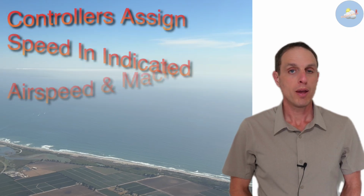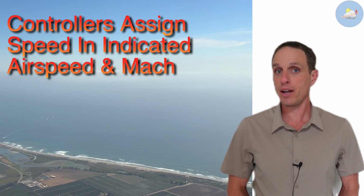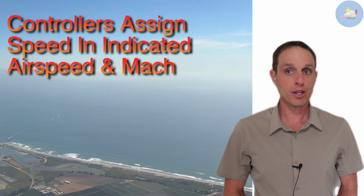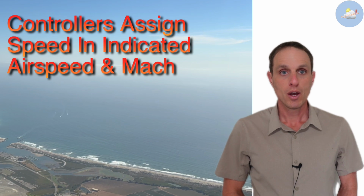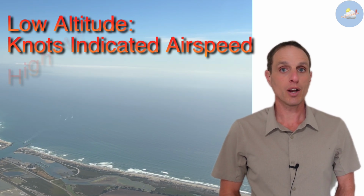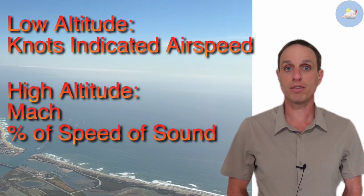So, why are we talking about all of these speeds? Because air traffic controllers primarily assign speeds using indicated airspeed and Mach number. True airspeed is not used because back when these rules were made, pilots didn't have a reliable way to constantly calculate it. For low altitude flights, controllers use knots. But at higher flight levels, they switch to Mach, or a percentage of the speed of sound.